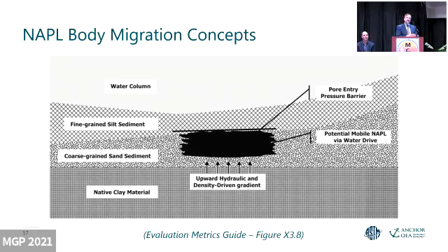And another thing we can look at using the hydraulic conductivity of the NAPL phase is, if it's able to move upward, what would the velocity of movement be? If the velocity is de minimis, if it would take 2,000 years to move up 5 feet to get to the mud line, that's important to know. And in a lot of cases, NAPL in sediments is essentially immobile.